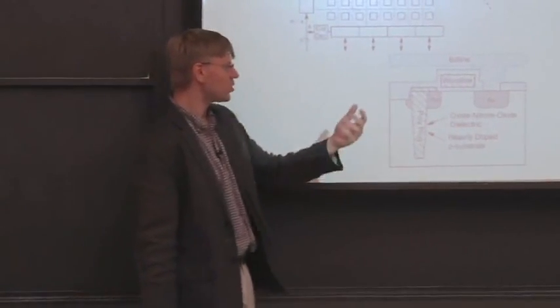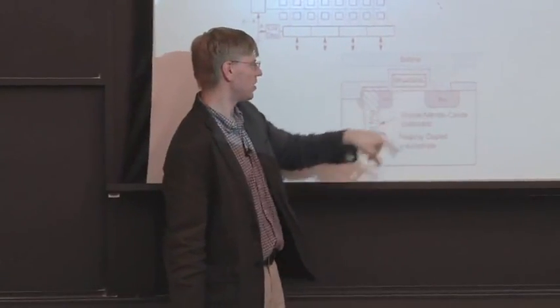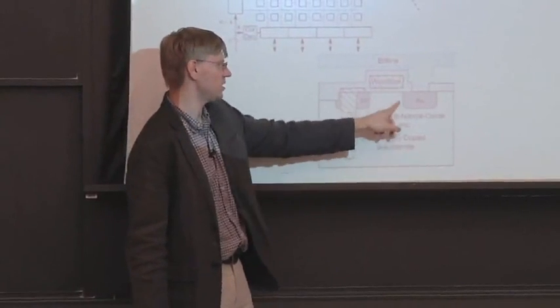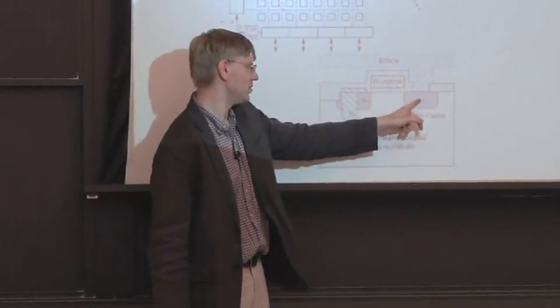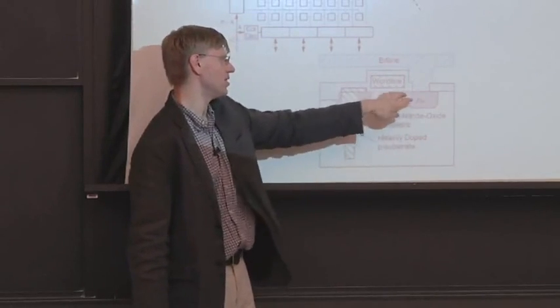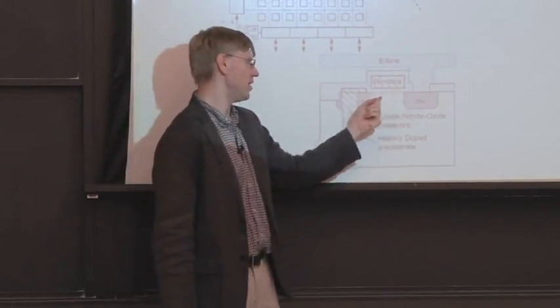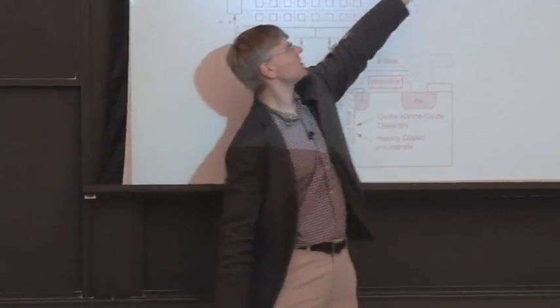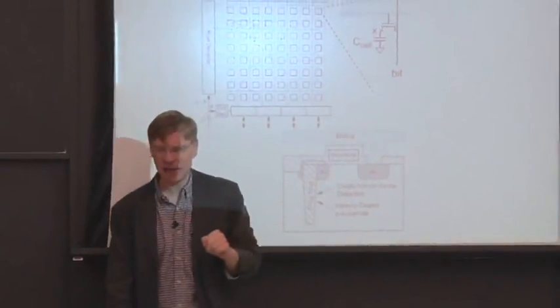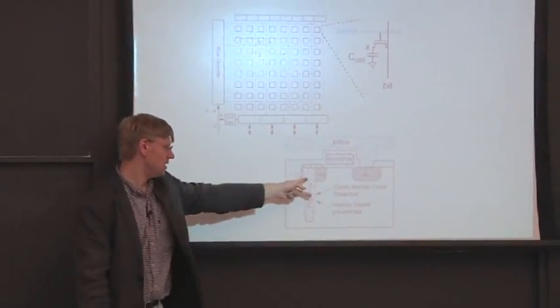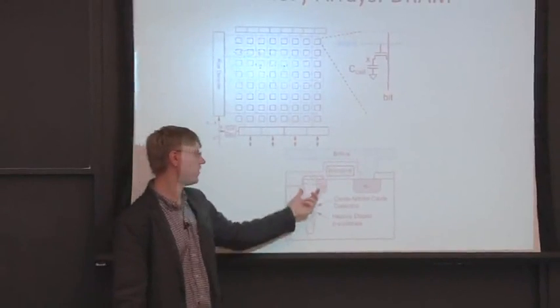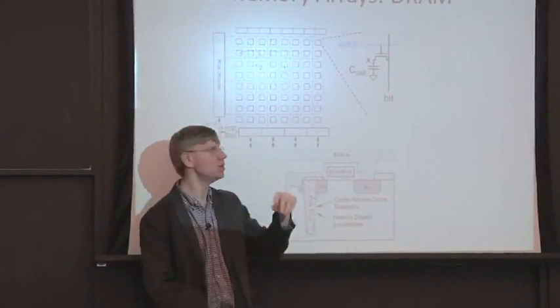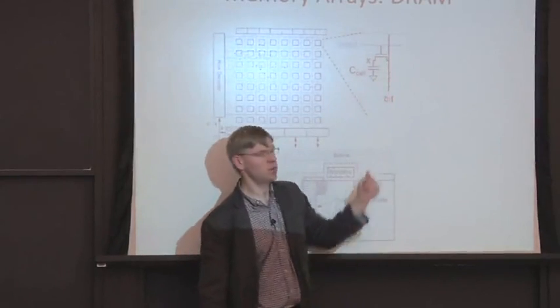And then all the actual logic is up here. So in this diagram here, this is the transistor, N doped, N doped, and here's the depletion region, and here's our word line. But basically, that's this transistor here. So we're going to be connecting the capacitor, which has a very funny aspect ratio, it's very tall, to this bit line.